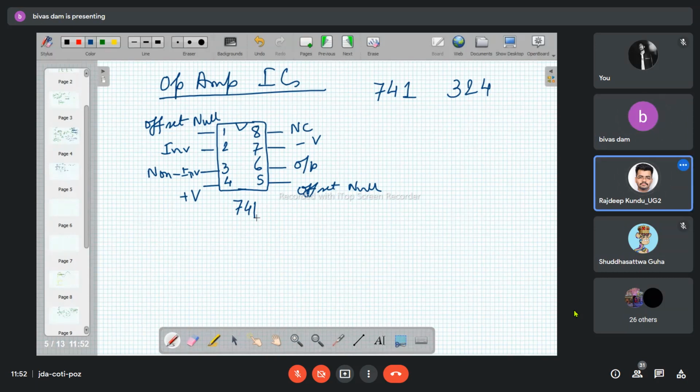Effective input offset voltage. Yes, sir. That is positive. So now through these null terminals, if you try to introduce a certain negative DC voltage level shifter state, it may so happen that for one particular such input voltage, the level shifter is now able to ensure zero output. But remember, that will also be valid for only that particular time instant. After 1 hour, the parameter conditions may be somewhat different.